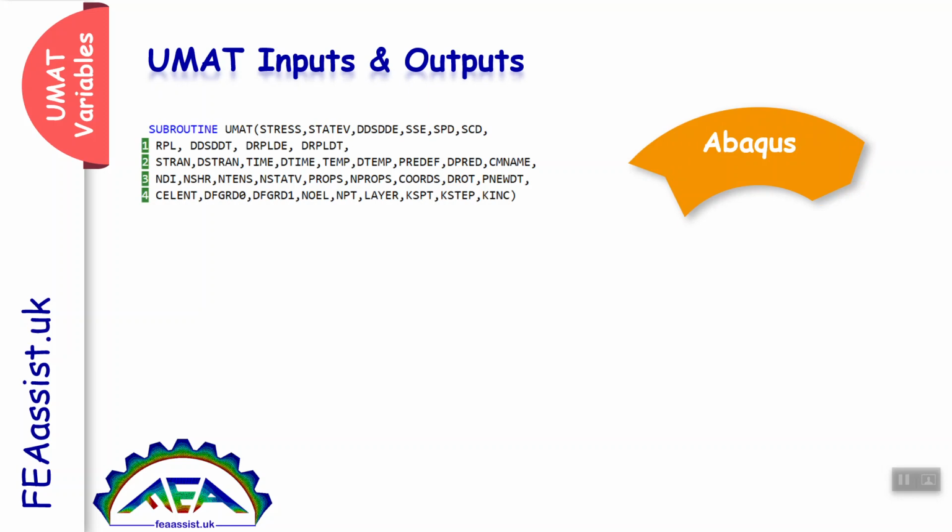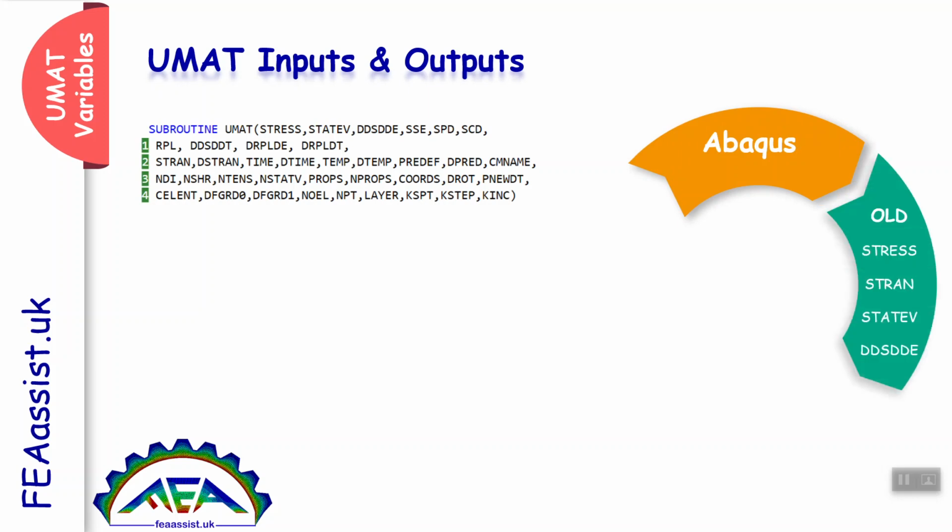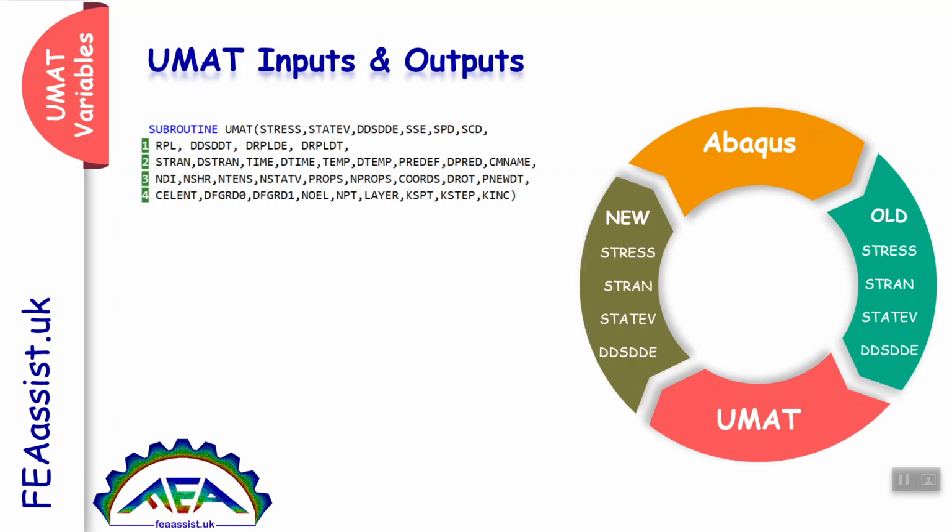Actually, all these variables are computed in Abaqus and transferred to the UMAT. In the UMAT, we need to write some equations based on our constitutive behavior to recompute all these variables and return them back to Abaqus. This is how Abaqus and UMAT interact with each other, which is necessary to write a well-working UMAT.